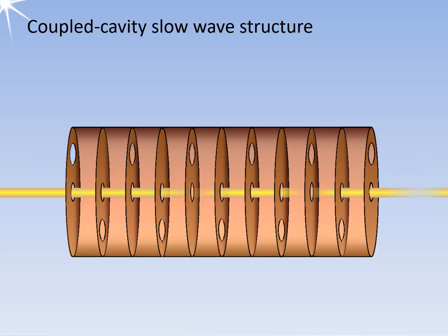In coupled cavity TWTs, several tens of klystron-like cavities are used for the slow wave structure. The electron current flows through these resonators, which have alternating slots, creating a coupled line. The RF path travels in a zigzag pattern through the coupling slots in the resonators, constantly crossing the electron current.